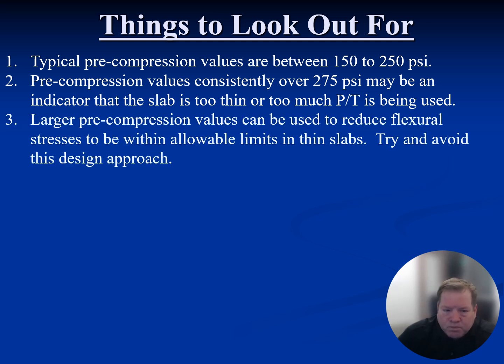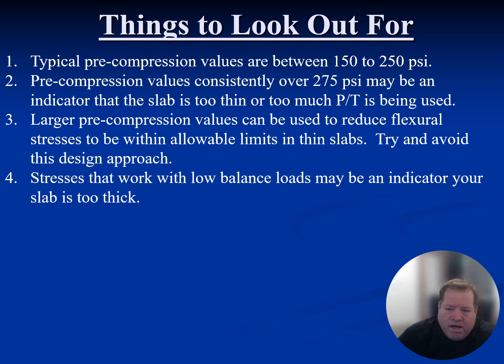Now, obviously, you can use larger pre-compression values to reduce the flexural stresses to make a thin slab work, and I've seen a lot of engineers do that, but take some advice from an old man, try and avoid that design approach. Oppositely, if you're using a design that works with very, very low balance loads, everything is 50% balance, 60% balance, and you're satisfying stresses all over the place, that's a good indicator that your slab may be too thick.